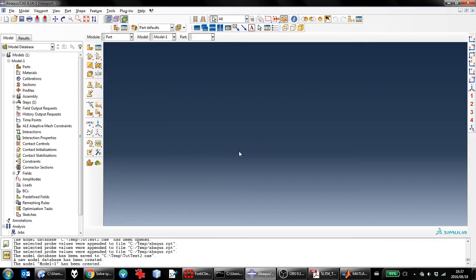Hi everyone, this is just a short video to showcase what you were supposed to do in the tutorial test to solve the problem on what I'm going to call a little bridge structure or beam structure supported by slanted columns. What made this problem a bit out of the ordinary was that you were supposed to model the column as a truss element and the actual beam profile for the deck as a continuous beam. Also there were some rotated supports and then the triangular load. So I'll get right into it.